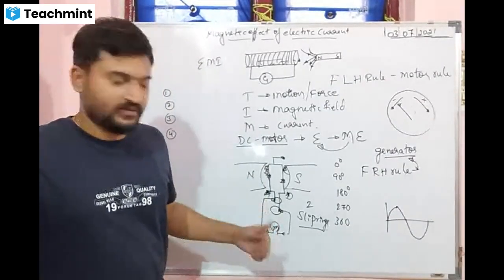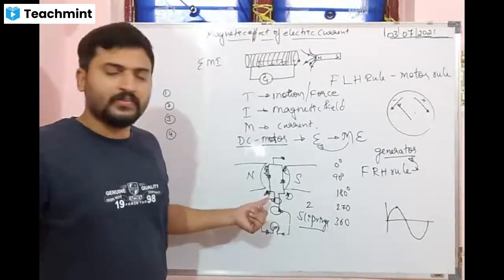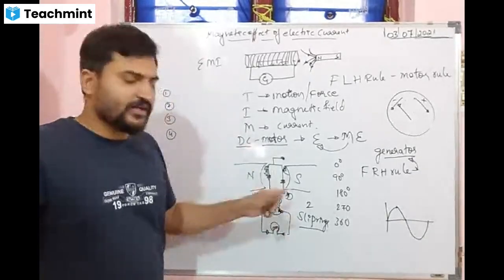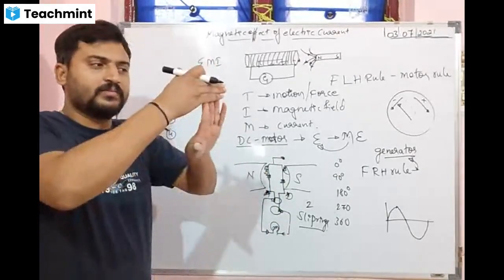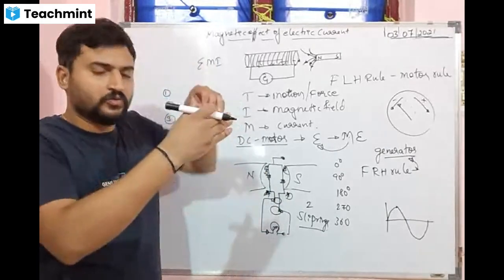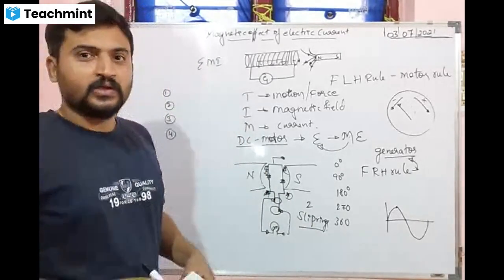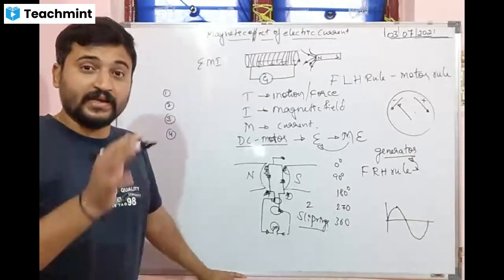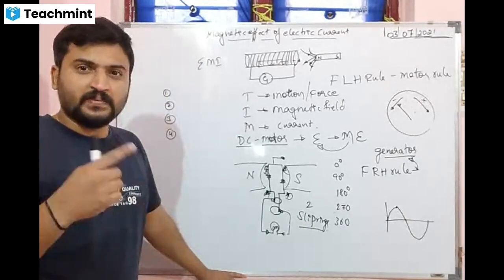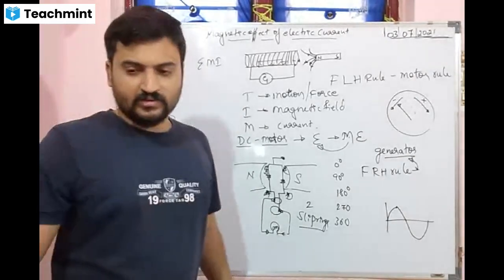Slip rings. So brush 1, brush 2, carbon brushes. Carbon brush because it will be continuously rotating. The brush stays connected and keeps rubbing as it goes. It will receive the current and send it outside. So carbon brushes are used to reduce friction and reduce sparks. If any other metal is used, sparks will start. So they use carbon brushes.